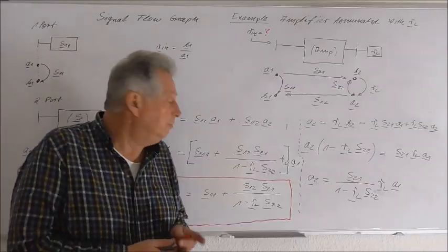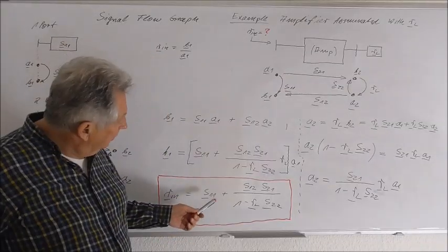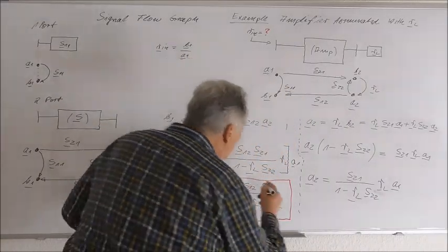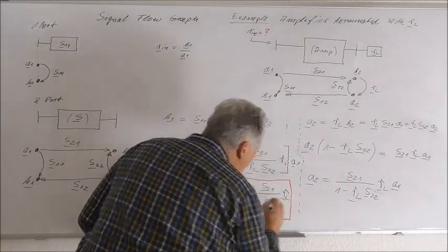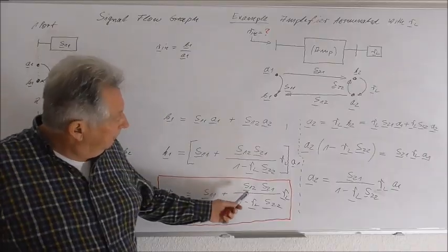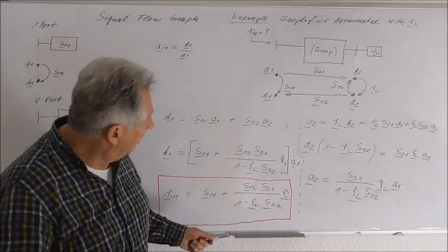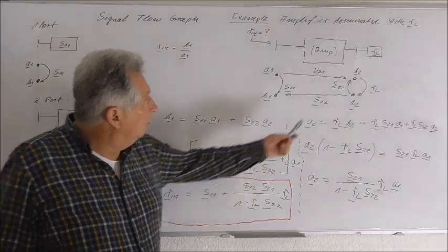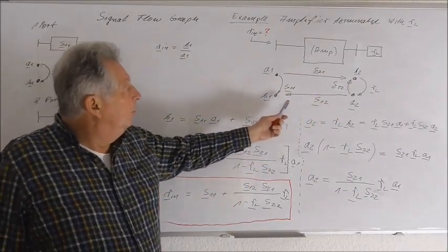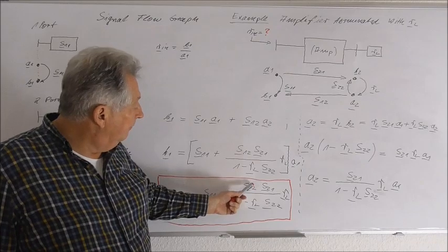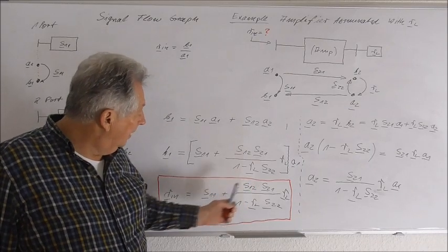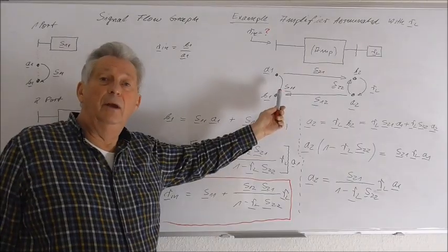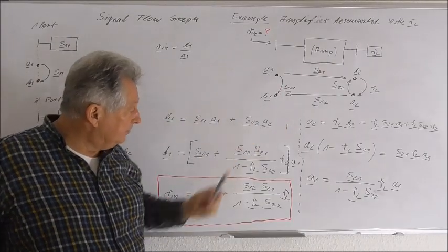And one point which is very important here, we see, oh, here our L is missing, I see. Our L is missing here. But a very important point here is that if the influence of port 2 on port 1 would vanish, so if this would be 0, then of course the input reflection coefficient would be given only by the S parameter S11 of the transistor.